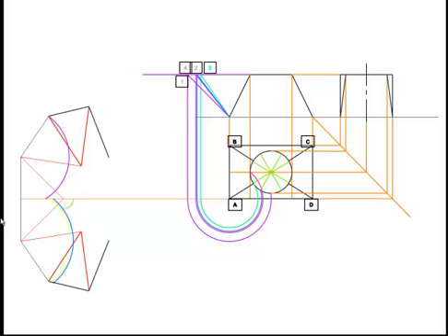Now we do the same thing again. We get the yellow line and swing another point, which will create another point in the development, and likewise again with the purple line. This will create 3 points in plan on the development, and again another point, which will be 4 points, which will be 1, 2, 3 and 4 in plan and brought over to the development over here.